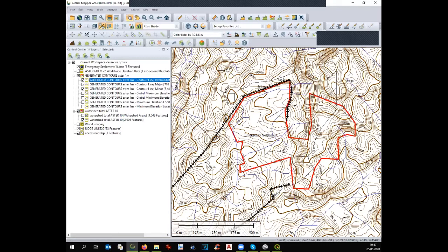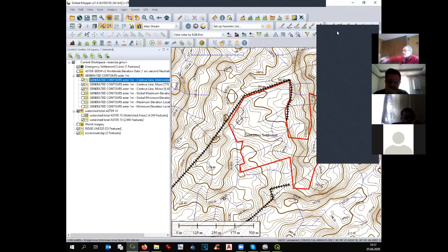How do you proceed? For me, from Global Mapper to AutoCAD, one single file into AutoCAD, and then you split in AutoCAD all the layers that I want. In one single command. So in that case, you visualize everything.